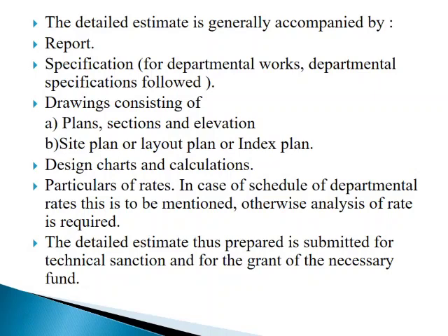The detailed estimate generally consists of, first, the report, next the specifications for departmental work or the departmental specification followed. Next are the drawings. We require drawings for this, because without drawings we cannot prepare a measurement sheet or an abstract sheet. The drawings include plans, sections and elevations for our quantities.